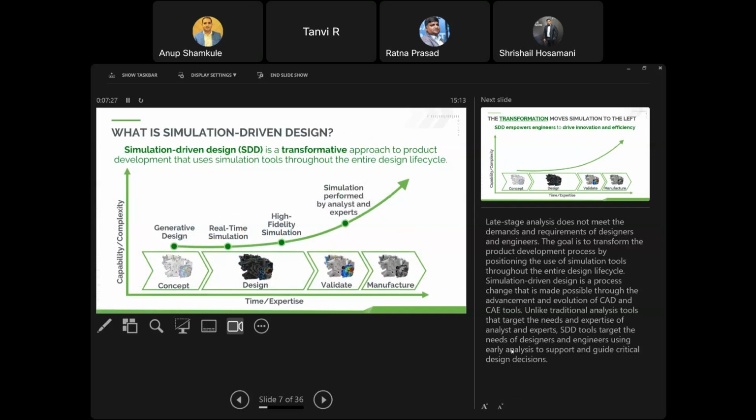Are we designing the best concept, or do we have time to explore different alternatives so that we finalize the best concept to proceed with the analysis, so that we will not be cutting back into the different phases, like how we saw in the previous slide, where in the traditional process of design you go through concept design, detailed design, and then when doing the analysis you get the model, do the meshing, apply the constraints, apply the loads, then go to the design phase and validate it.